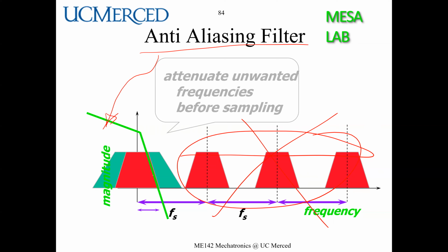You can stop in here, so it will be fine. In all data acquisition systems, you have this anti-aliasing filter inherently built in. That's why you are fine. You don't see it, but it's there. You should know that. Anything you sample will have duplicated spectrums like this, but you can low pass filter it if you sample fast enough.